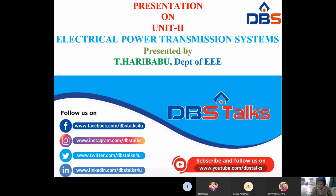And H parameters are also there, where input voltage and output current V1, I2 must be expressed in terms of I1, V2. But out of all these parameters, ABCD parameters are well suited for transmission lines. Why? Because we know the receiving end voltage and the receiving end current. From that receiving end voltage and receiving end current, we have to determine the sending end voltage and sending end current, right?